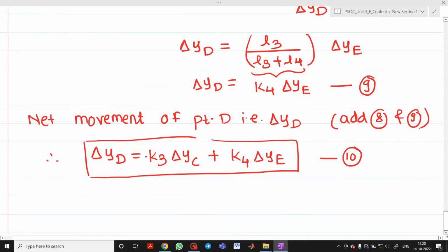So at this stage, there are some justifiable simplifying assumptions. So what are the assumptions here? Inertial reaction forces of the main piston and the steam valve are negligible compared to the forces exerted on the piston by the high pressure oil.